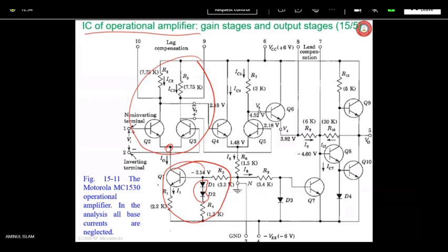So yeah, and you see, we have seen this table earlier also. For RL equals to 1K, it was 144 kilo ohm. For other values it may be different, okay? But at least 144 kilo ohm is quite high compared to 3 kilo ohm. So actually, this combination of these two resistances will not be much affected. I mean, this 3 kilo ohm will not be much affected. It will persist. I mean, 3 kilo ohm will only persist.